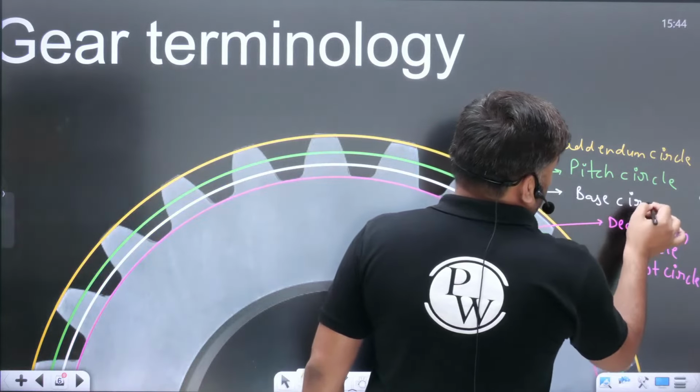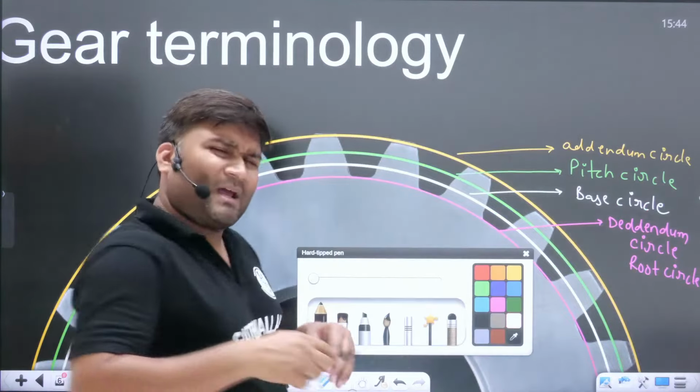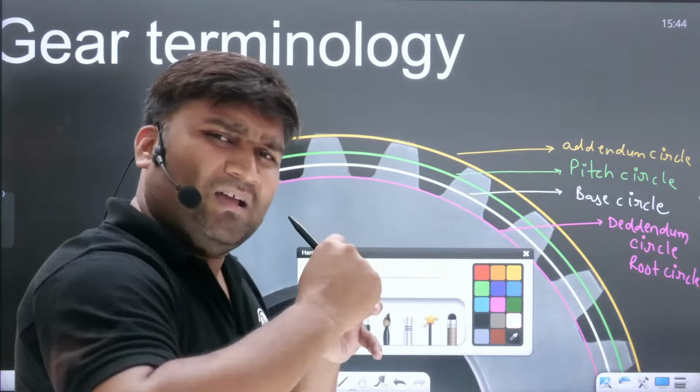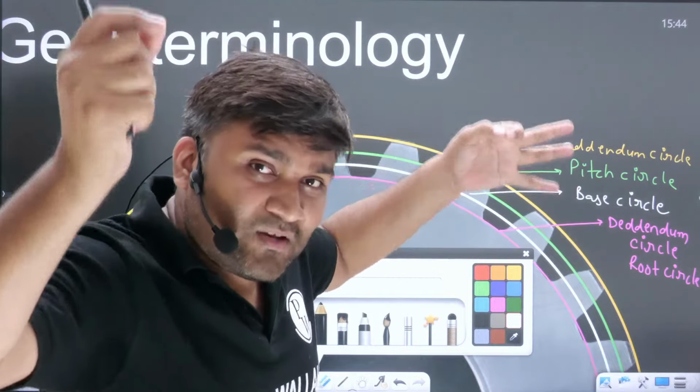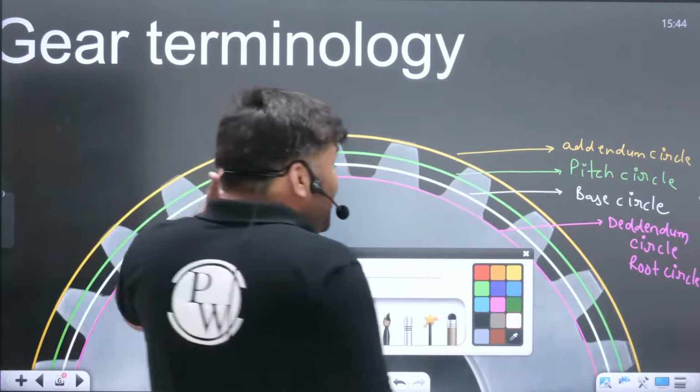And somewhere below the pitch circle you have your beautiful base circle. Now, on the base circle, again you have done the same thing: you have taken a thread, opened that thread, and you have got some involute curve. Now everybody can imagine, you must know that the involute curve which you are going to get will be above the base circle. Can you imagine, beta?